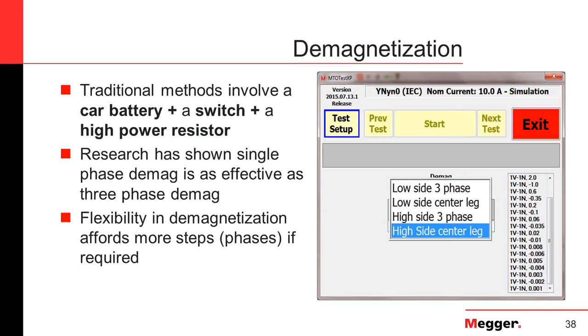Now, in our test equipment, because some customers want to test all 3-phase or demagnetize, we have allowed that. Even though it is a sense of stability that people would want, and so we allow that to happen, it is better judgment. As well, what we have learned is that we need to apply more steps. We do not do very coarse steps. We start coarse and then we run very fine in order to bring the transformer to a closer state of demagnetization.